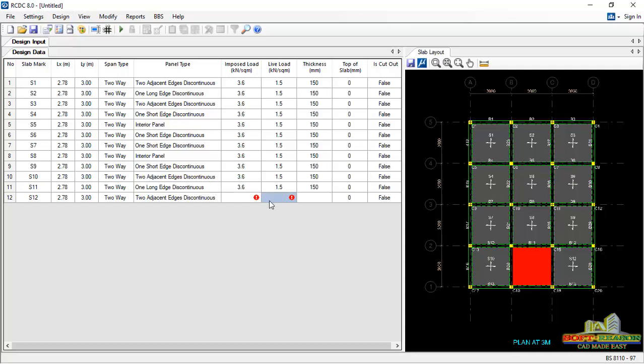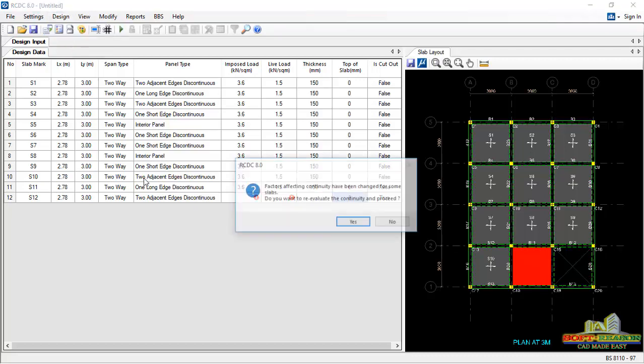So it can't design because this provision is empty. What I intended doing in this provision, if I select this now, I will make it true. It's false already, I'll make it true just like that. If I make that true, you can see there is no more slab in this provision, meaning I'm going to consider these provisions for my stairway, this staircase provision. So I'll go back to the design again and click on auto design.